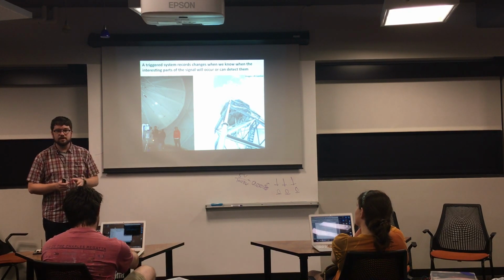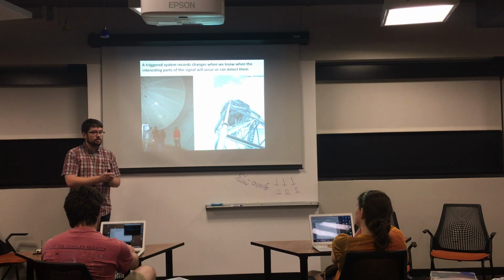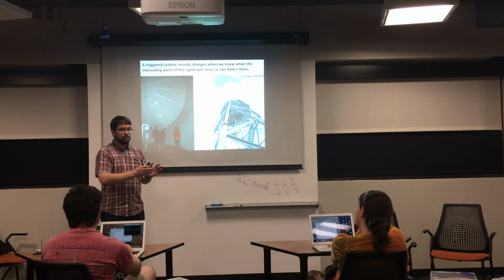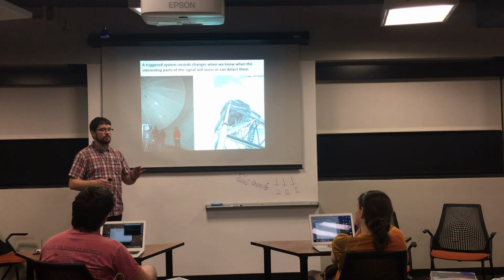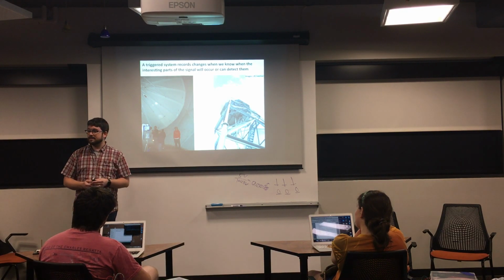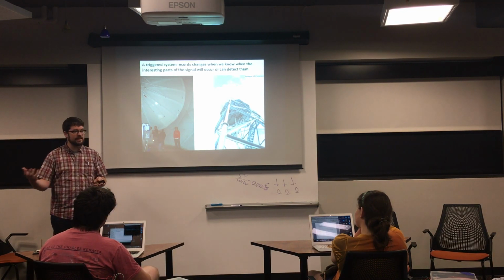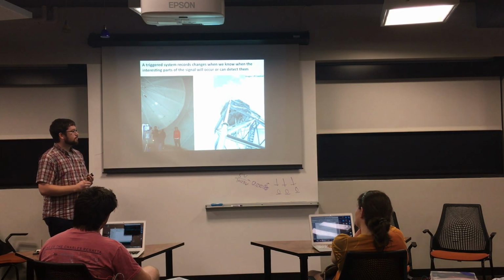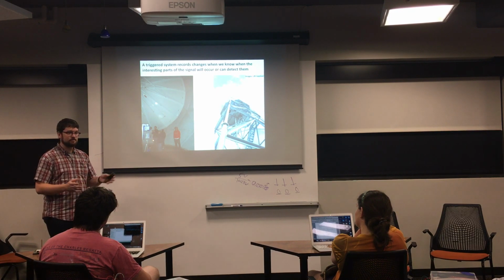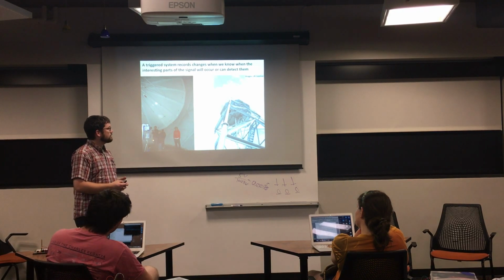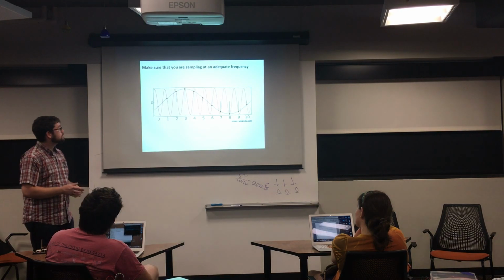So like in the lab when we do acoustic emission, we don't record, well, we do sometimes, but we shouldn't be, recording at 50 megahertz for 3 hours. That's an incredible amount of data. And in fact, there are very few data acquisition systems that can do that because you have a problem of how do you get that much data written to any kind of storage media. Even solid state hard drives would struggle to keep up. So then you have some kind of buffer, and the buffer fills and then you have to stop. So it's still effectively triggered. So for really high rate things, we use trigger acquisition.